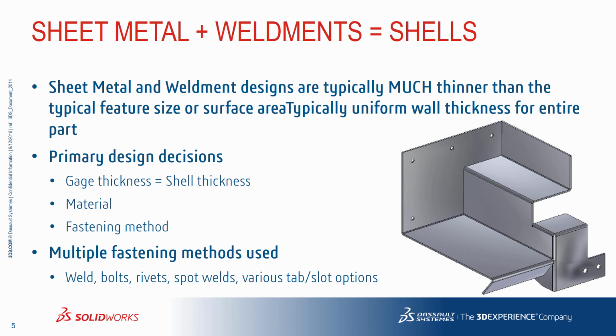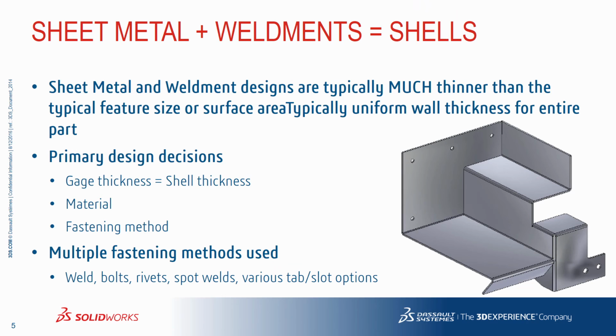So when we look at shell elements, why do we need them? Well, typically because solid would just be too inefficient. If you look at the sheet metal part on the right, if I want to mesh that with a solid, remember that to get good bending stress with a high quality tetrahedral, I need about 2 elements minimum across the thickness. Okay, so if this is 20 thou sheet metal, that's going to be an extremely small element type. And that's just for this one solid part. What about when I get to assembly size?